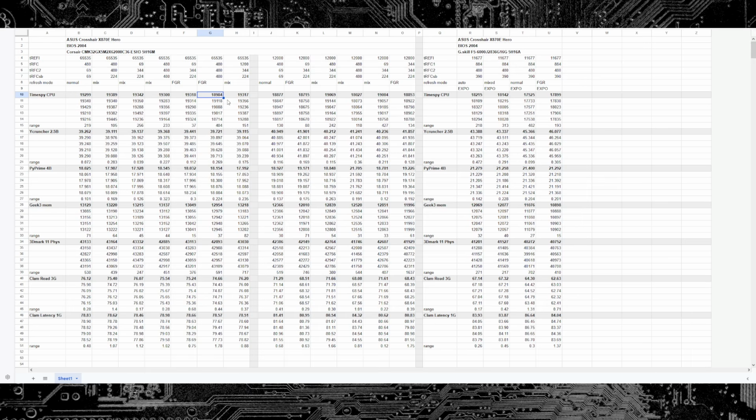Just don't do that. Now, admittedly, with Hynix ADI, 16 gigabit ADI, you're not going to get such massive differences in terms of what tRFC values you can run. For ADI, I think it's going to be 400, 300, or maybe 400, 280 or something. But with 16 gigabit MDI, you can run tRFC SB super duper low, right? 224 is not even minimized. I think I did try 180 and that doesn't post, but maybe 216 or something might actually still be viable, which is honestly kind of crazy.